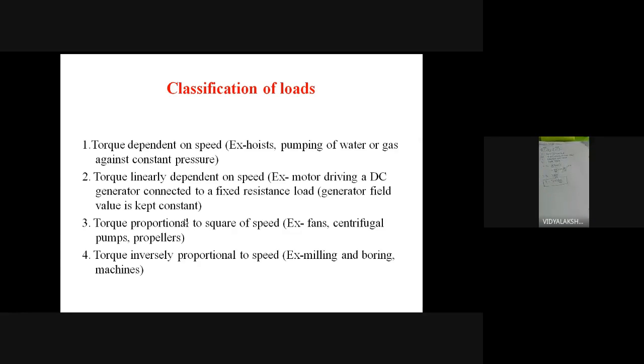The next one, I'm going to integrate with respect to the U and V method. So first I have J into d omega m plus omega m into dJ by dt equal to 0. For constant drive, I have chosen constant inertia, which is nothing but my dJ by dt equal to 0. So for that, I have rearranged that.